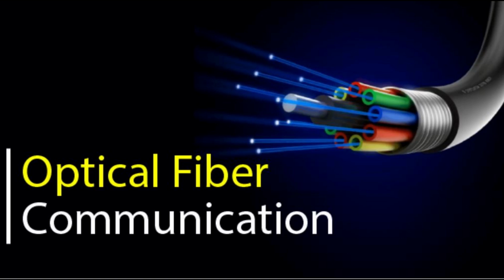Single-mode fiber. Single-mode fiber is used for longer distances due to the smaller diameter of the glass fiber core. This smaller diameter lessens the possibility for attenuation, which is a reduction in signal strength. The smaller opening isolates the light into a single beam, offering a more direct route and enabling the signal to travel a longer distance. Single-mode fiber also has a considerably higher bandwidth than multi-mode fiber. The light source used for single-mode fiber is typically a laser. Single-mode fiber is usually more expensive as it requires precise calculations to produce the laser light in a smaller opening.